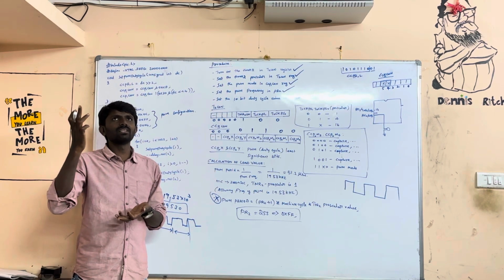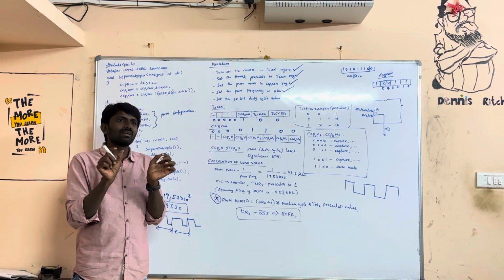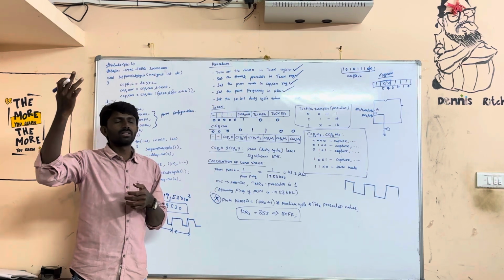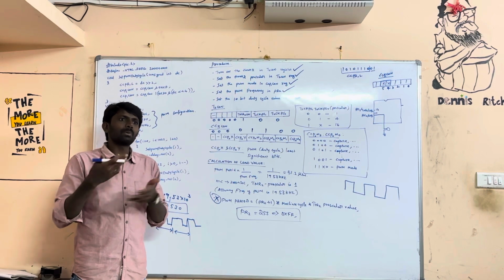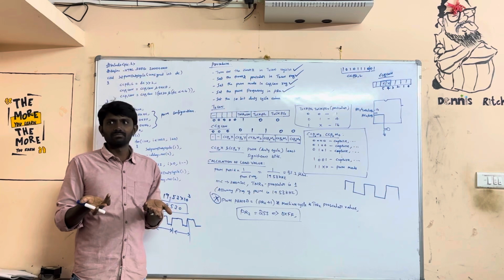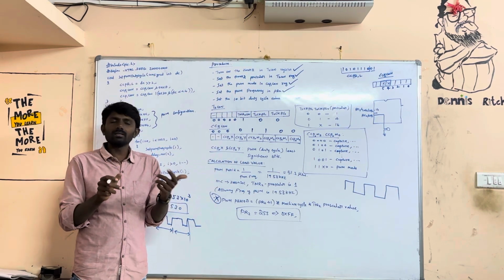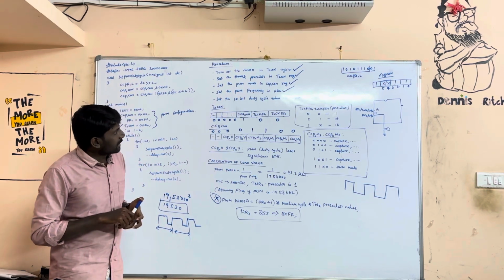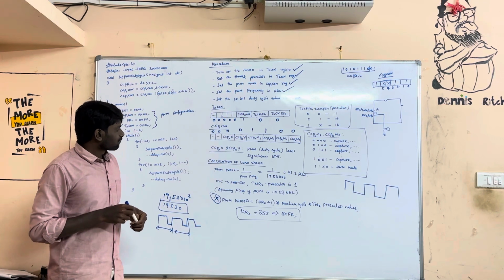For this ADC we discussed which register, ADCON. If you are able to recollect now, that is good. For ADC we discussed ADCON0 and ADCON1. ADCON0 is for 4 configurations, ADCON1 is for 2 configurations. Because I keep practicing, it comes to me. If you are able to recollect, that is super. But at least recollect what configuration you are doing. That is needed, that is expected. Okay, and that's all.